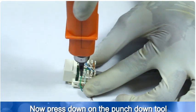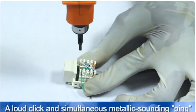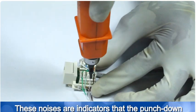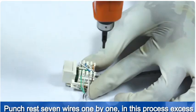Now press down on the punch down tool until you hear a loud click and simultaneous metallic sounding ping. These noises are indicators that the punch down has been done correctly. Punch the rest 7 wires one by one.